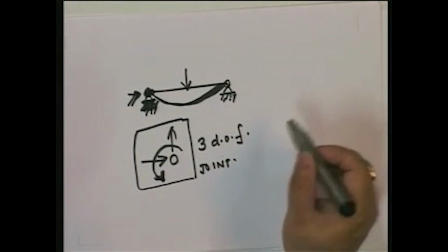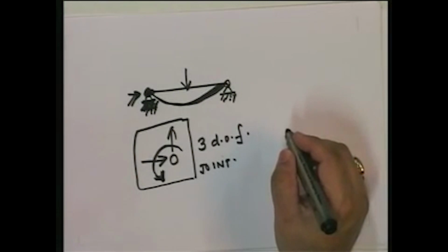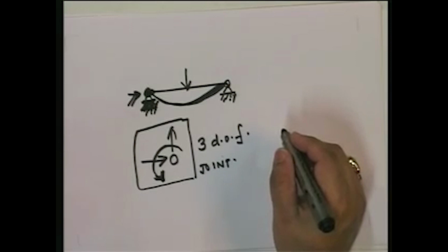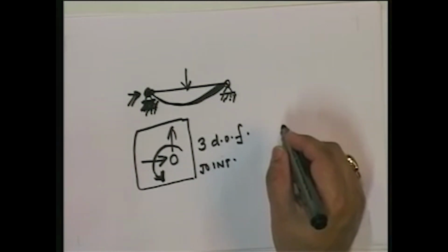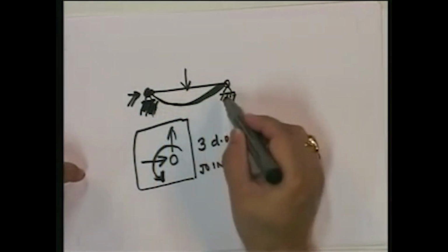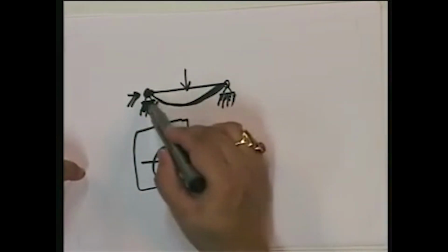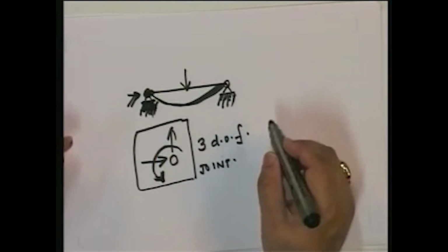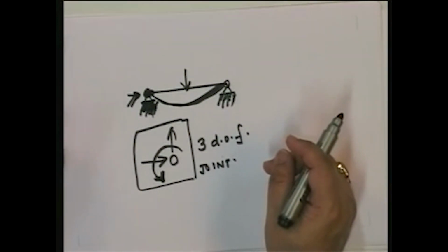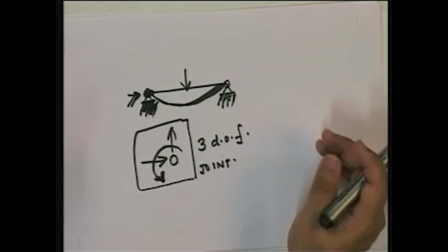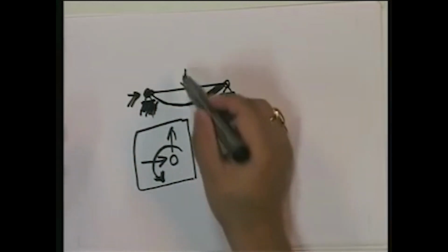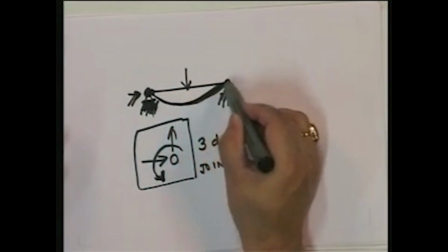Does that mean that, remember, if I have a kinematically determinate structure, I can define the displaced geometry of the structure completely? Can I? Think about it. If I restrain this and I restrain this, both the displacements are restrained. Both the displacements are restrained means what? No displacement. But is that true? No. Under this load, it displaces in this manner.